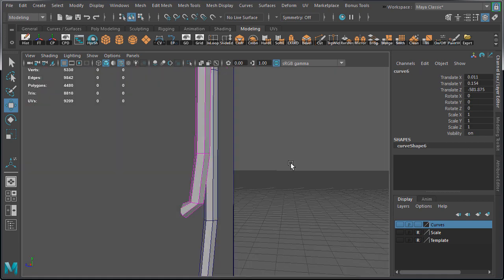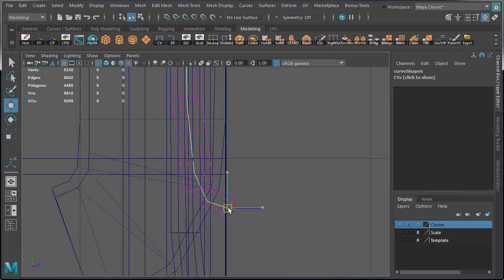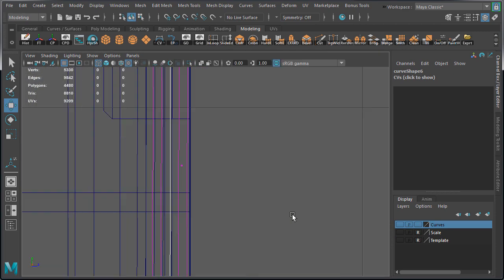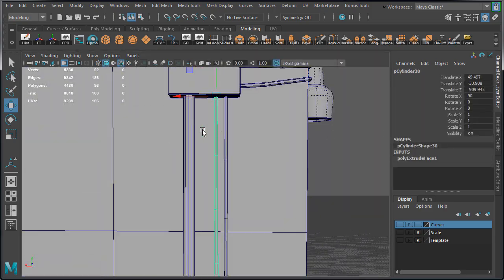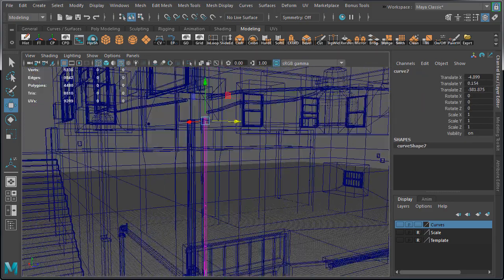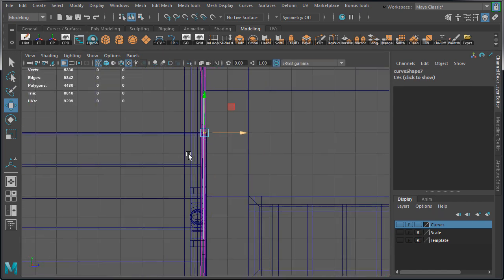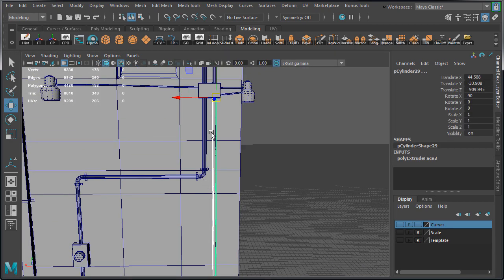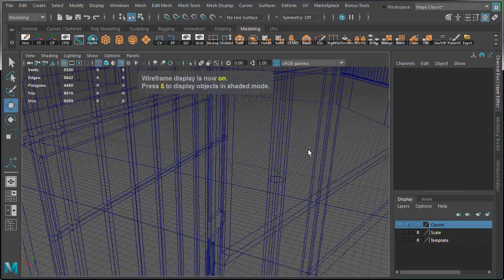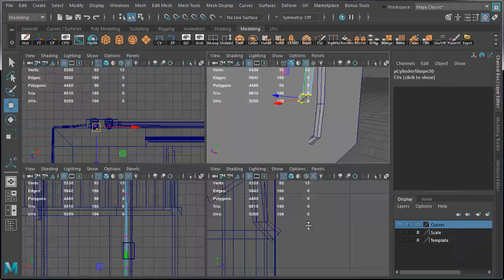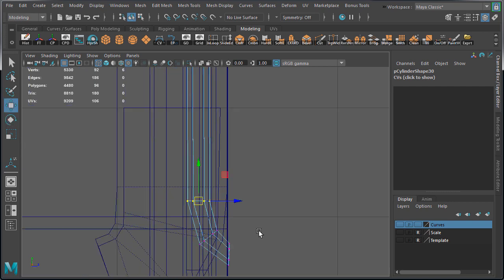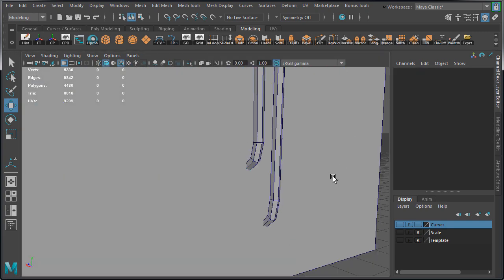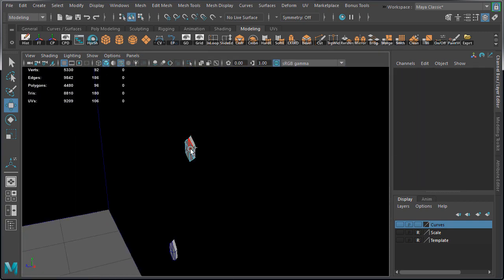And actually, this could be a very quick way to create a wire network. If you have a large set of similar size and length wires, just create one curve, reshape it, then duplicate the curve multiple times and reshape each one. Then duplicate a bunch of template cylinders, position them next to the curves, and extrude each cylinder along the curve. And you can get something very complex going very quickly, especially after you've done a few extrusions along the curve and you know the steps and technique. This process can be duplicated rather quickly.